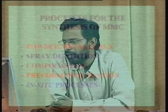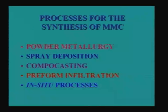A number of people are working on such things, and the other thing is called compo casting, also called stir casting. In the stir casting technique, you again take the liquid metal, add the reinforcement particles to it, stir the liquid so that they are uniformly, homogeneously distributed, and then pour this slurry into a mold and generate a casting out of it, and that casting would be a composite casting. So this is what is called compo casting.